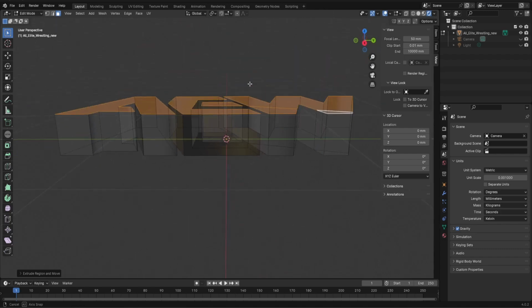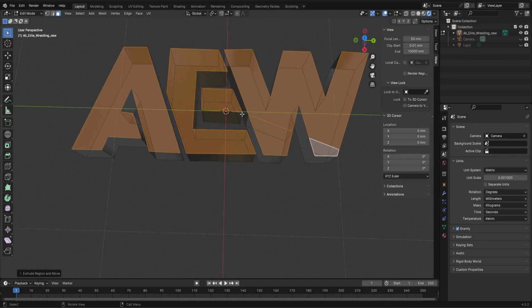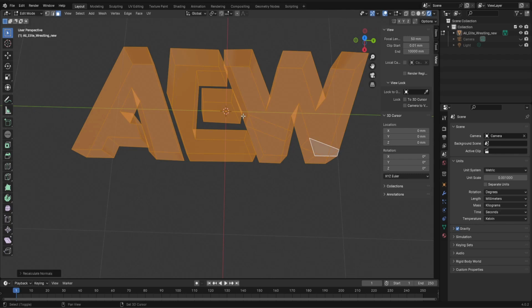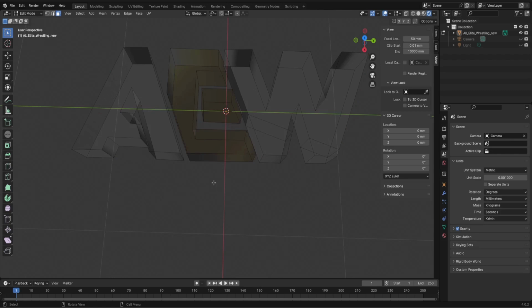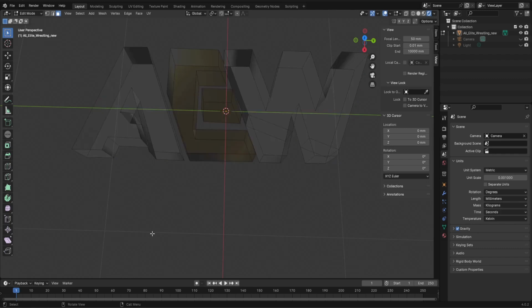If you are worried that the texture might be transparent and it might not be working right, there is a little shortcut that we can do. And that is to select everything. So what you do is you press A to select everything, and then you press Shift and N. N for normals. And what happens is a little thing comes down here saying recalculate normals. You should always do that with whatever object you're doing, because it flips all the normals to the top.